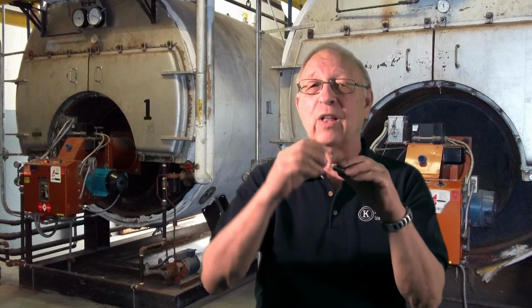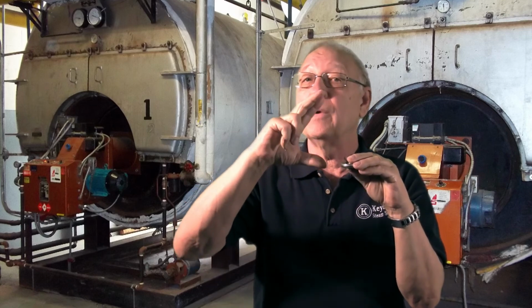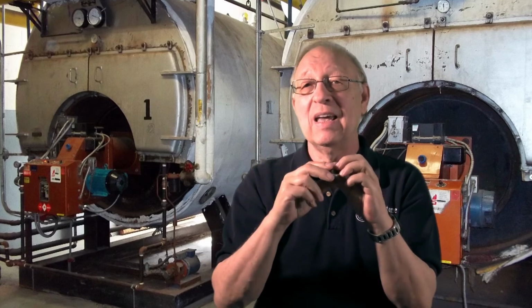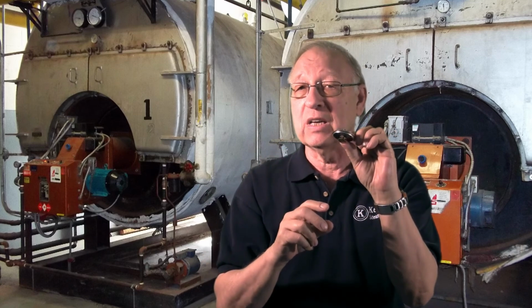As long as the system is in operation, it constantly monitors the flow, stopping the steam from escaping until it's given up its energy and then letting the condensate go back to the boiler. The bellows is constantly flexing, opening and closing, and eventually it will rupture due to metal fatigue and need to be replaced.